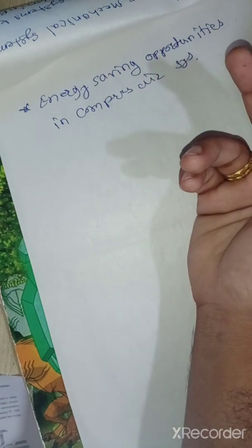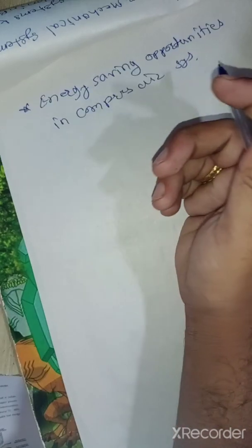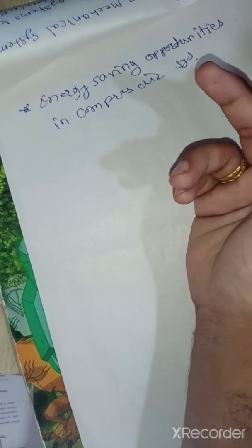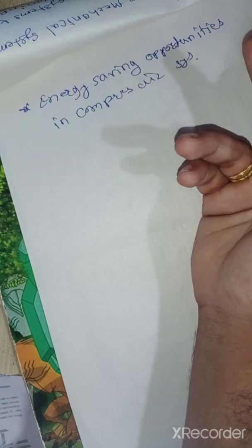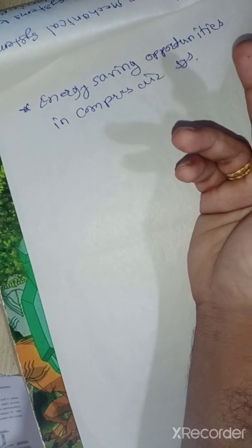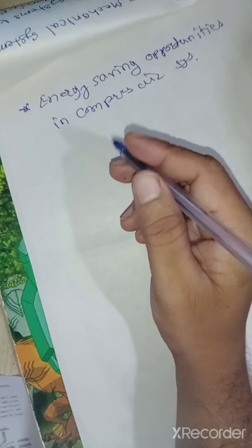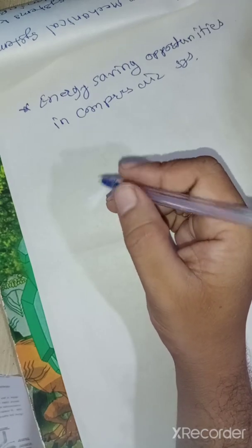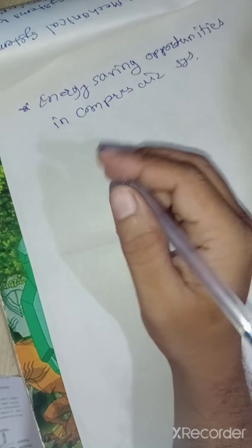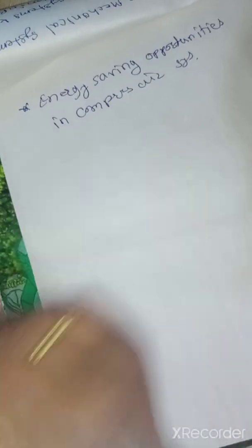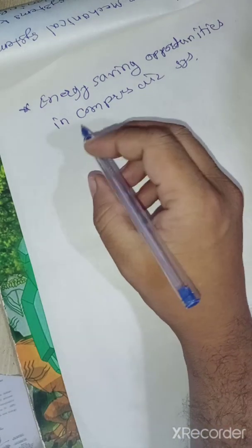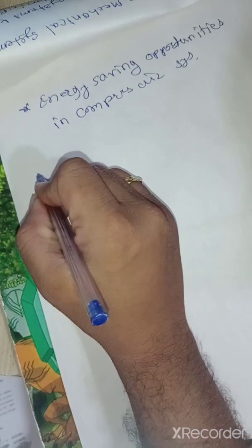Only 10 to 30% of energy reaches the point of end use, and the balance 70 to 90% of the energy of the prime mover is converted to unusable heat energy, and to a lesser extent lost in the form of friction, misuse, noise. So the leakage problem, actuation problem, blow conveying, tools, these are wastages in a compressor. Suppose I draw a Sankey diagram for this.